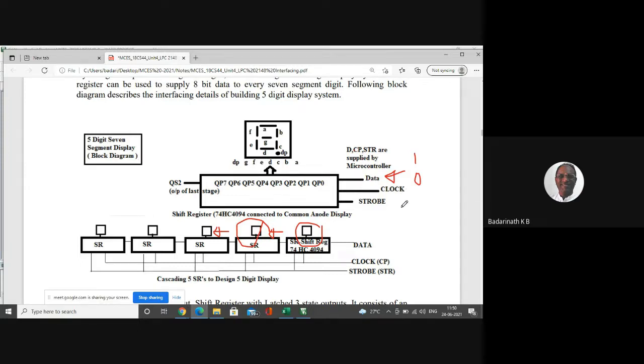So what is the way? I can generate a clock pulse like this. One, I can generate it with this method. This is called a positive edge clock signal. So what is a positive edge clock signal? I have to apply it on this clock line, which is a single pin, P0.20. So I have to first place a logic 0 here, yes or no? Then give some delay and then make it 1.